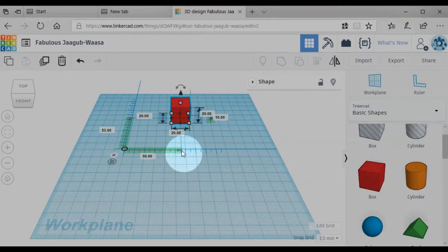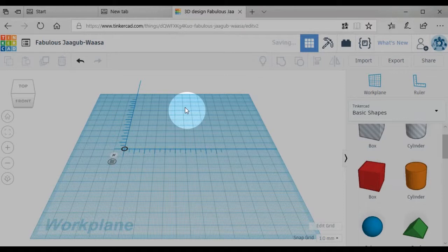Using the midpoint in all of the lessons in this series will add some consistency and help people focus more on the software and not so much on the calculations. For this reason, set the ruler to measure to the midpoints by clicking on the toggle so that the label reads "Use Endpoint." The ruler will now measure distances to the center or midpoint of objects.